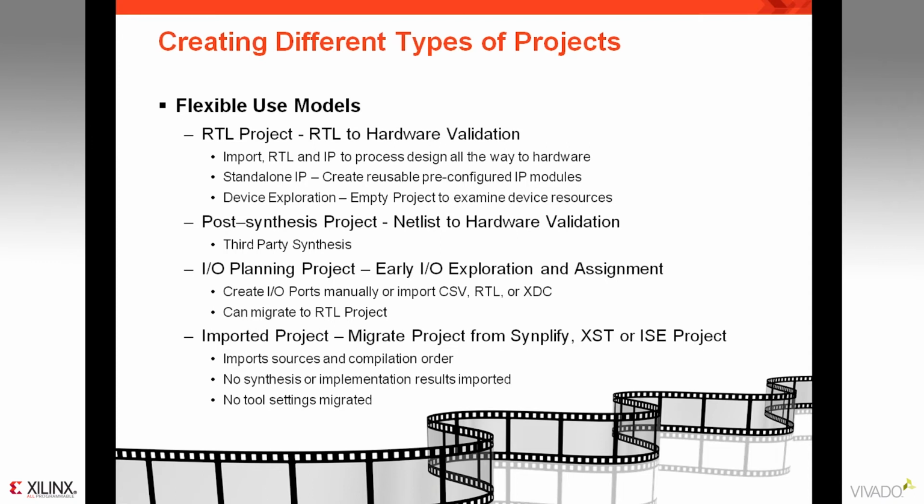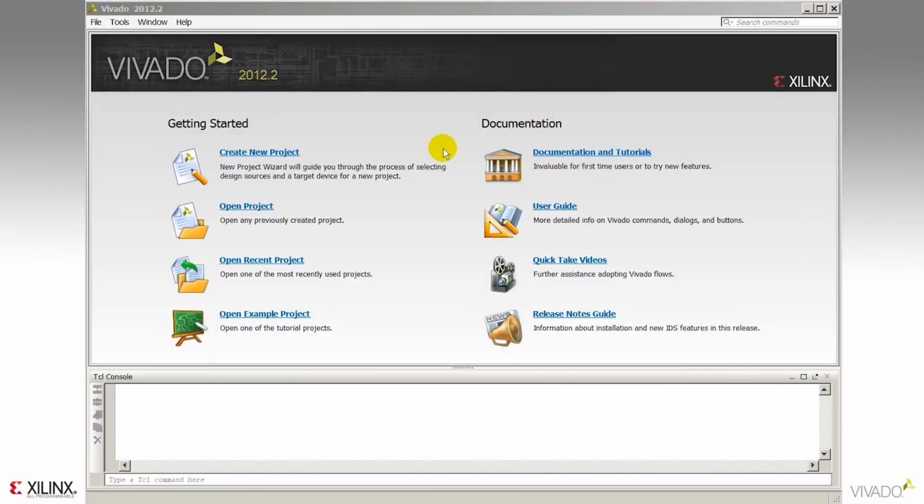And no tool settings are migrated. Since the Vivado and ISE tools are not really compatible as far as tool settings go, we've elected not to try to make that migration for you. Now we'll walk through the process of creating each one of these types of projects.